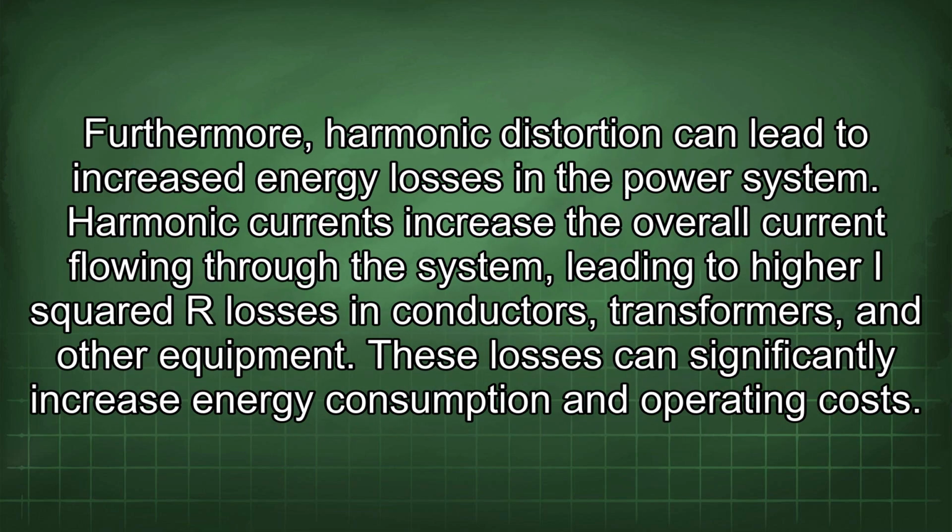Furthermore, harmonic distortion can lead to increased energy losses in the power system. Harmonic currents increase the overall current flowing through the system, leading to higher I²R losses in conductors, transformers, and other equipment. These losses can significantly increase energy consumption and operating costs.